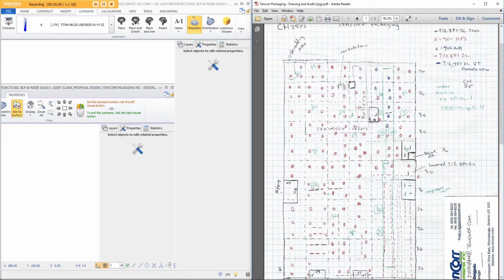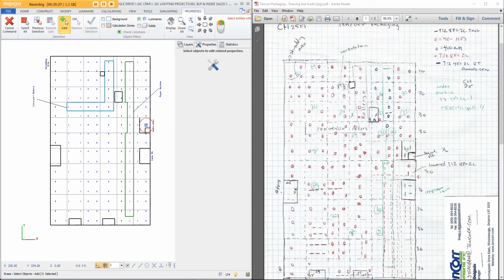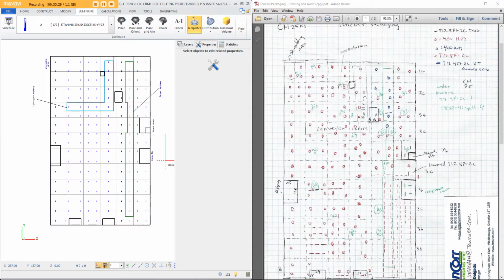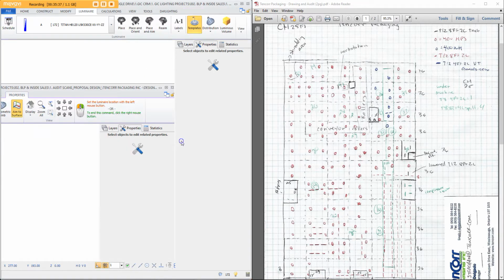The maintenance department, we have here T12 8-foot 2-lamp fixtures. So any black line minus the surrounding in the building is going to be just a retrofit as well. So what we can do here is we've got another one here. So these are lowered task lights. Let's remove, we're going to remove this one and this one here. I'm going to move this light up a bit, about centered to these ones here.